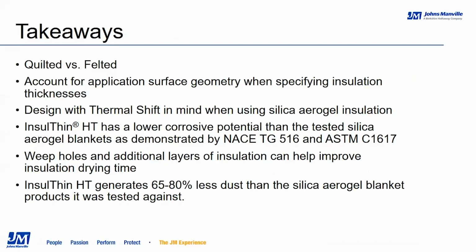Now, you should also design the system with the assumption that water infiltration is an eventuality by considering the corrosive potential of the insulation materials that you select for your system. And you want to do this in the design phase. Keep in mind that even though each material passes its own standard specification, as you saw in that graph earlier, just because it passes a standard specification doesn't mean the performance is all equal. Each material has a different corrosive potential.